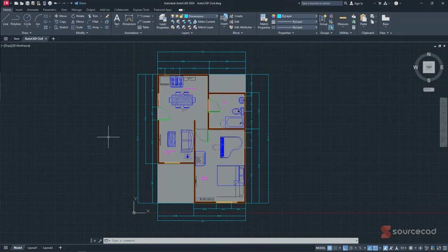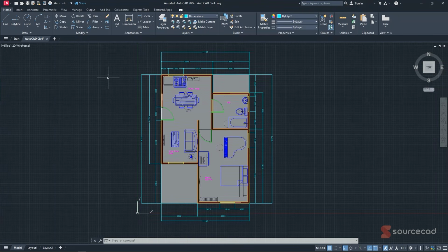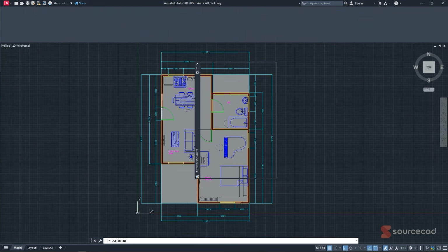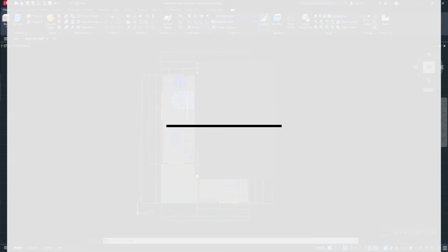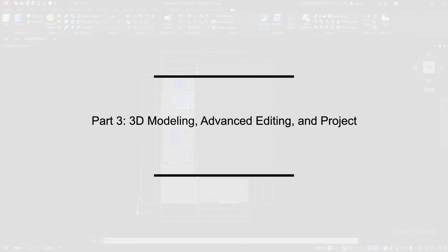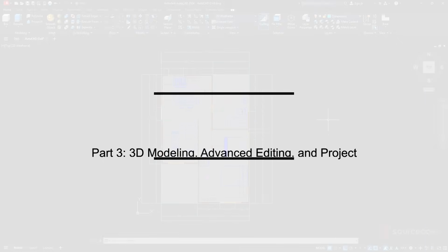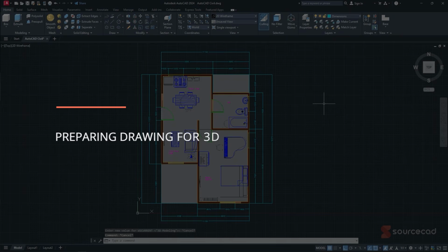The 3D modeling part is not usually found within this 2D area. So for one to be able to access it, you can change the workspace from this point just by clicking on this arrow, and you can change from Drafting and Annotation, which is usually the default that comes with AutoCAD, to the 3D Modeling workspace. Just click on this once, and you'll see that the entire workspace will change to look a bit different. It looks a bit different because now it's more focused on the 3D part of AutoCAD, which I'll be taking you through. Still, the same options are more or less still there.